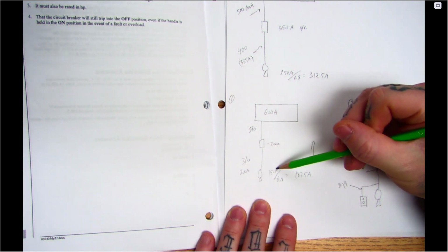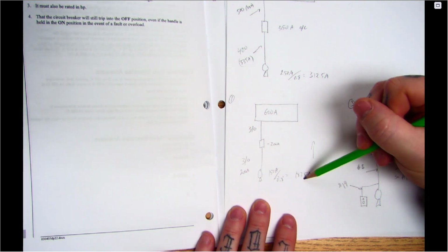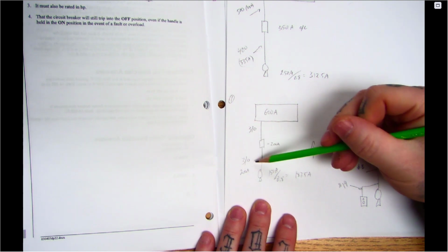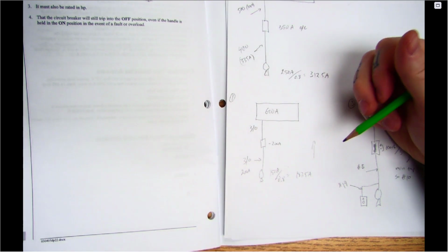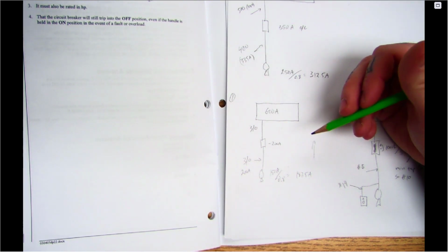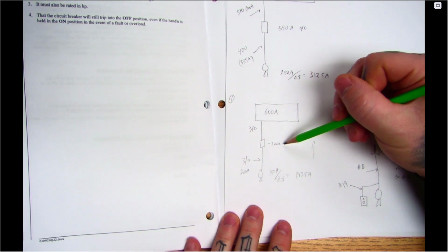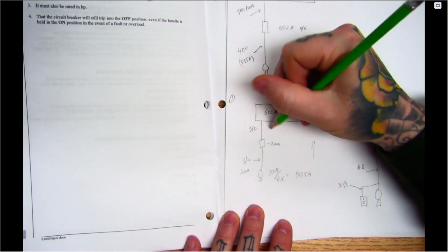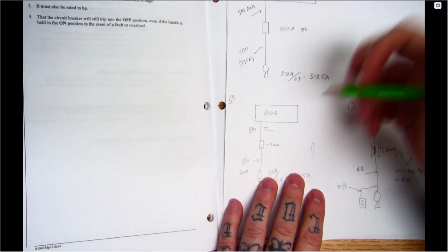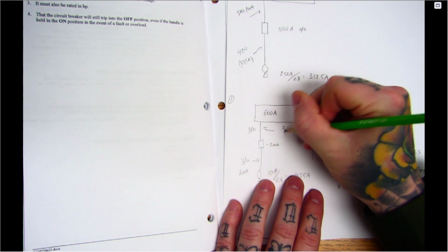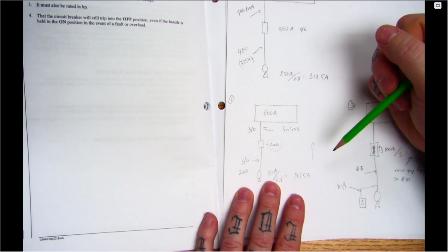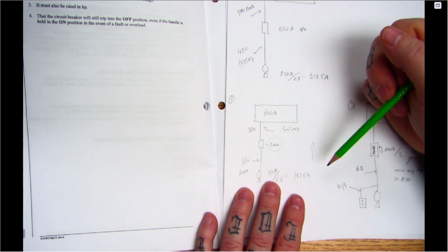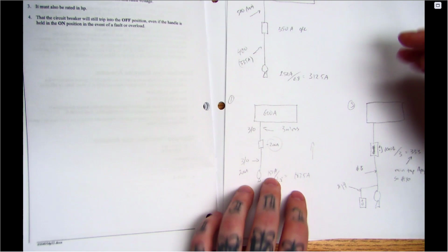So I took my 150 divided by 0.8 because it's continuous, got my inflated ampacity, then sized this conductor off of that. So I used a 3/0 off the 75 degree table, which is good for 200 amps. So then I would have a 200 amp overcurrent. Now, because they said the taps are not greater than 3, so 3 meters or less, then we get into a scenario where we're using this to size our conductor. So we'll use 3/0 there for that tap conductor.